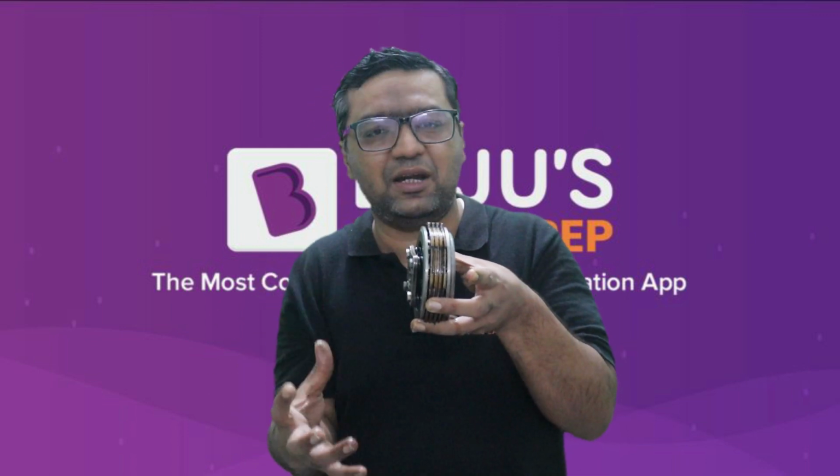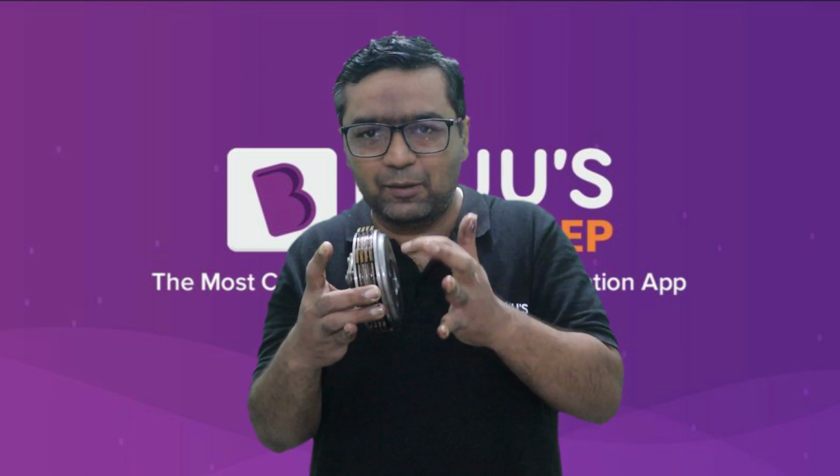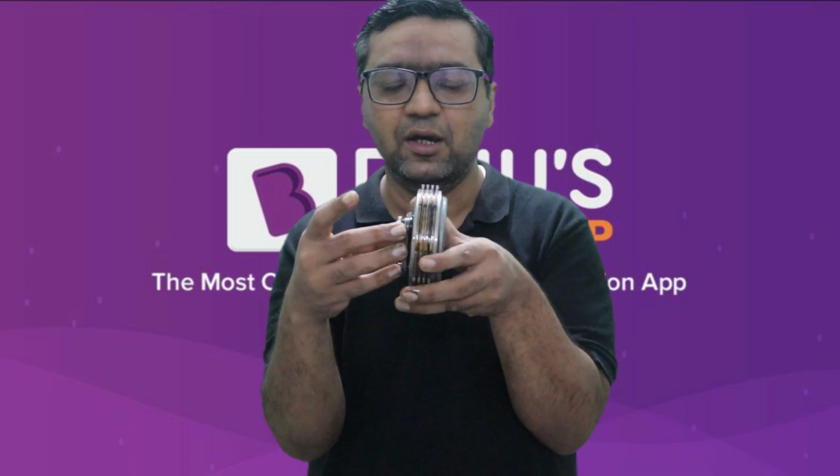Whatever power will be transmitted will be transmitted with the help of friction. Here the engine will always be giving power, always. In normal condition these springs are compressed, and because of that compressed condition the complete assembly is tightly fitted, and because of that power will be transmitted this side.